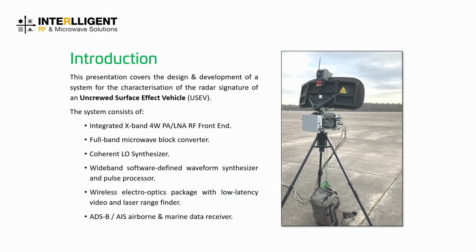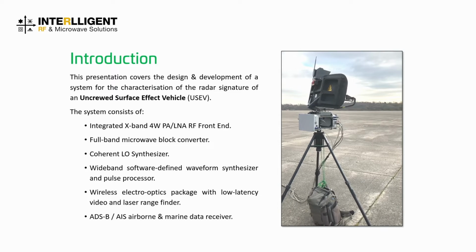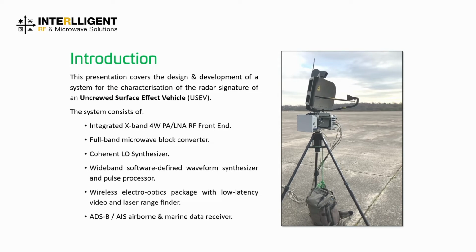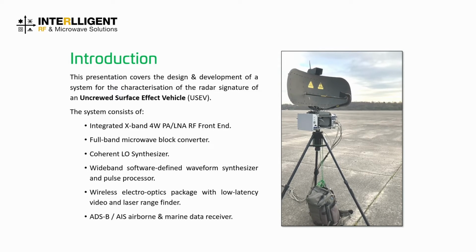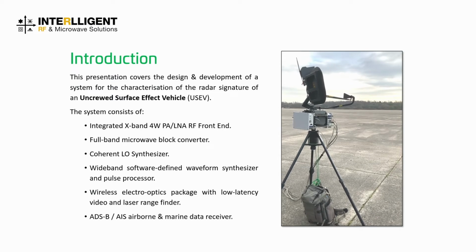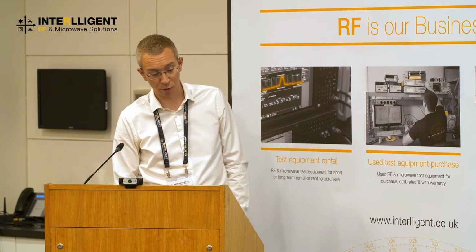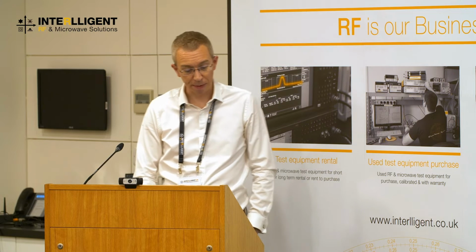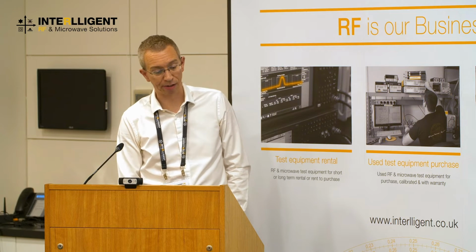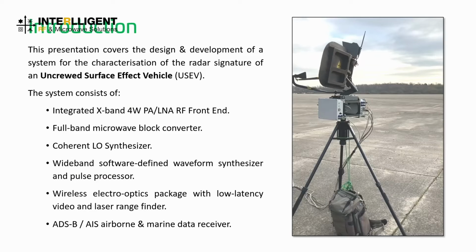So the system consists of an X-band 4-watt PA LNA front end, a full block down converter up converter, coherent LO, wideband software-defined waveform synthesizer, a wireless electro-optics package, and also an ADS-B AIS airborne and marine receiver.